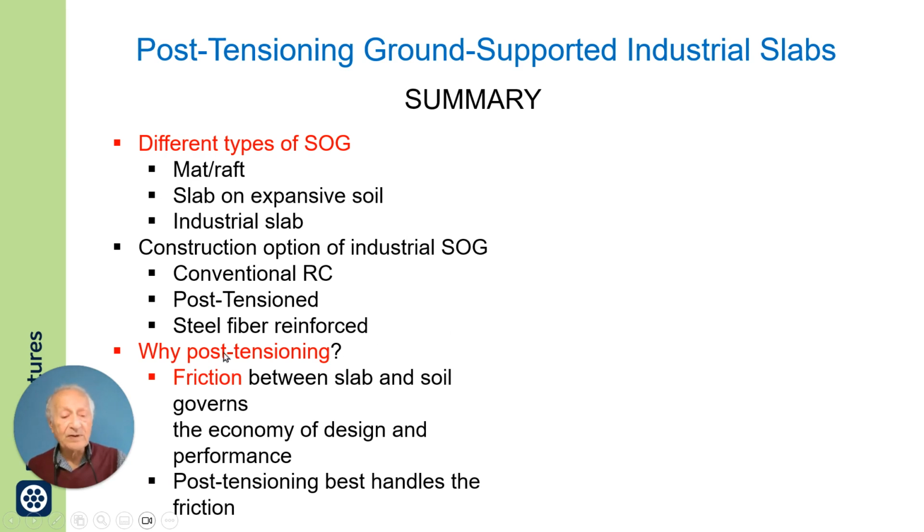Why we use post-tensioning? Because post-tensioning can move the ends of the slab toward one another to close the shrinkage cracks which are inevitable.